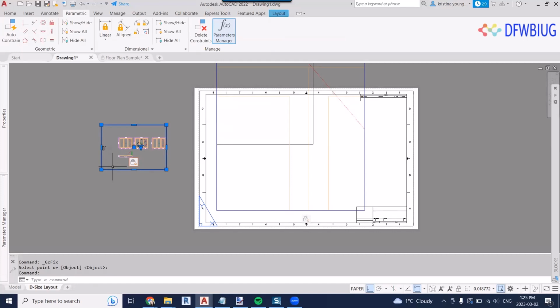I create all my viewports from an object. That way I can reshape the viewport. I can make an irregular shaped viewport and use the grips. So I always make it from an object. I don't use the regular make viewport. So you use the curves and stuff for your viewports as well. Yeah, sometimes it's very interesting.